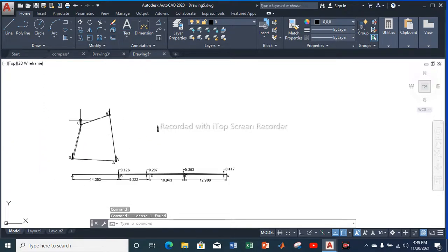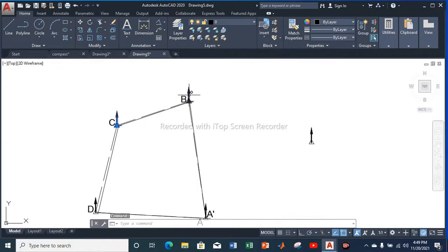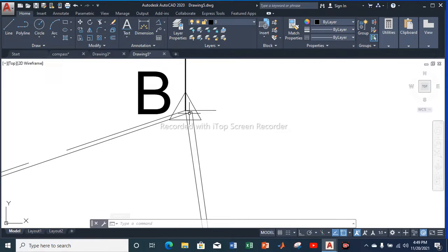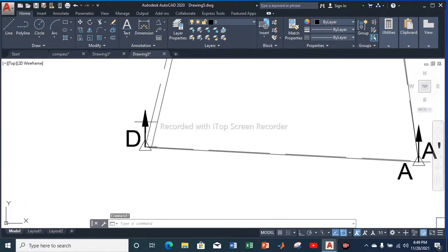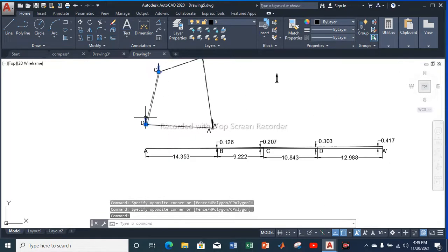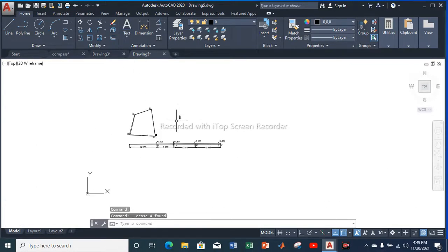Next, as you can see, all our station markings are now in our incorrect points. They are in our incorrect traverse. We need to change the station marks from incorrect to correct as well. So select all of them and click on delete. Now select this,